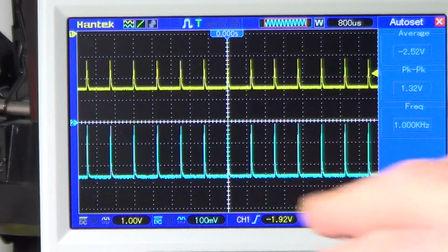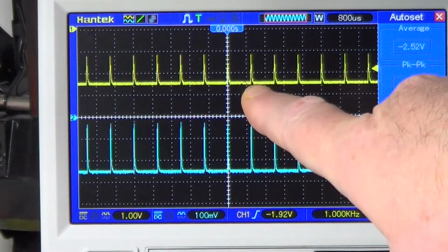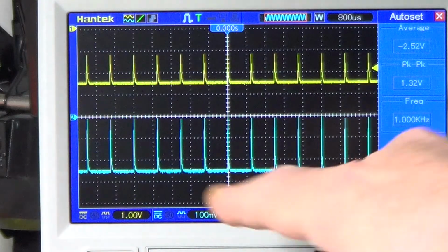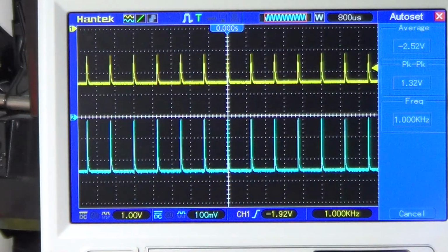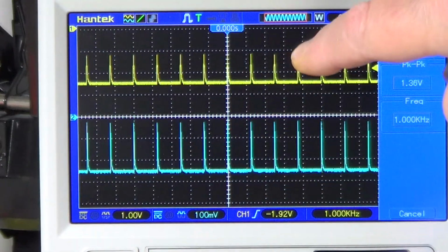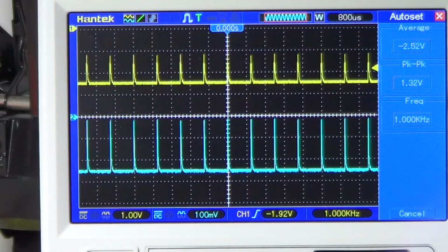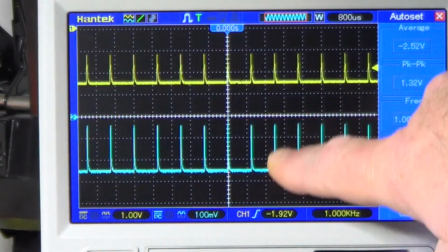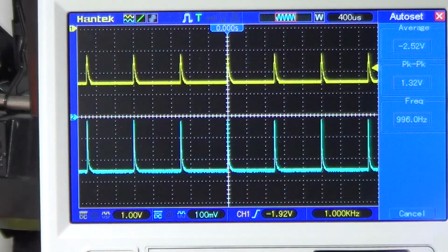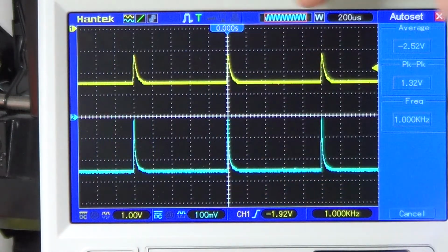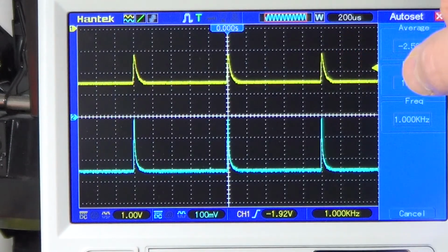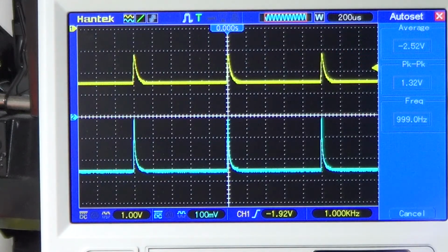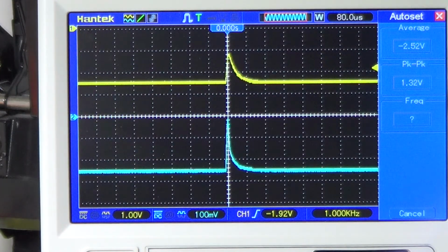And here's the response to an impulse. Again, this in yellow is the second order filter, while the one in blue is the first order filter. You can see how the second order filter is again a little smoother than the first order. Here the peak is much more pronounced. Let me enlarge it so you can see it better. See? In the second order filter there is a much smoother descending of the signal on the output of the filter. And that is because, again, this filter is cancelling more harmonics than the filter of the first order. Let's try to isolate one.